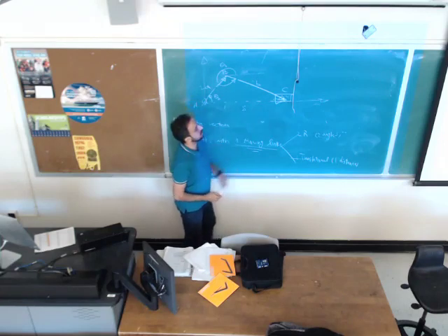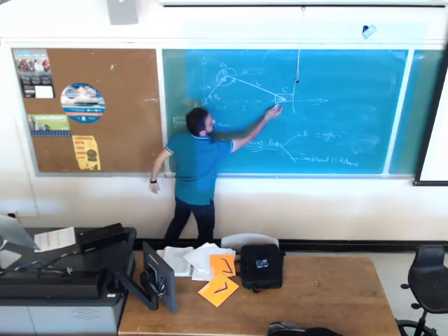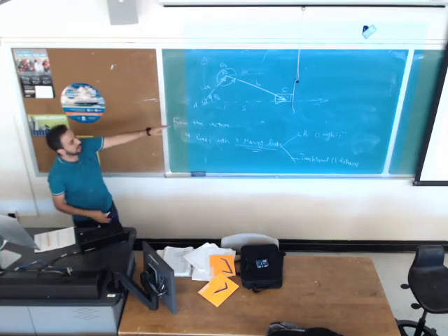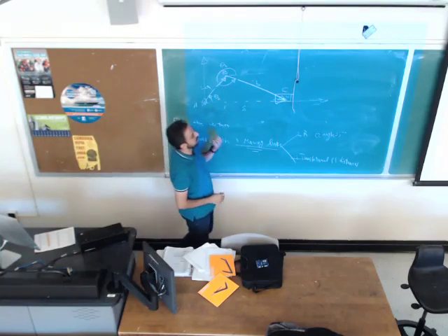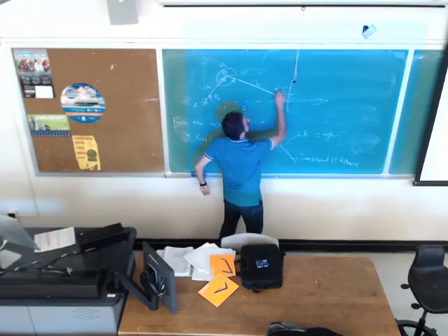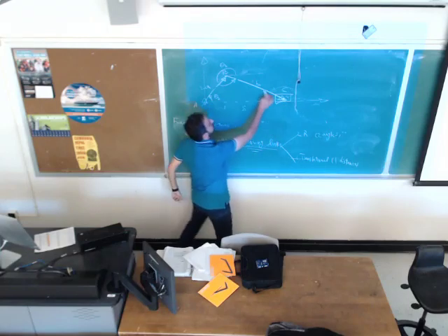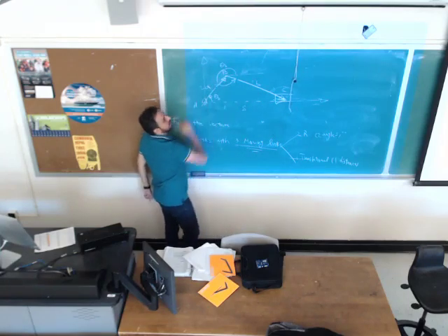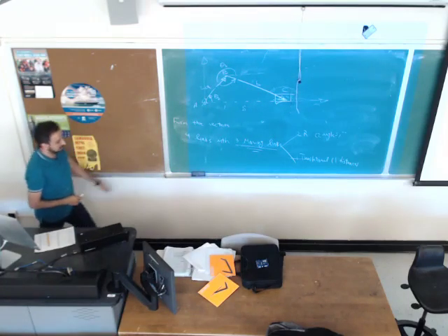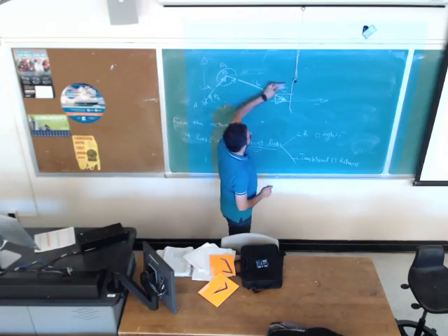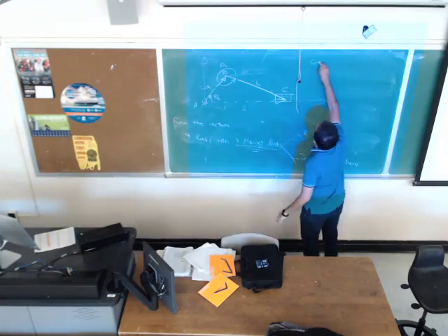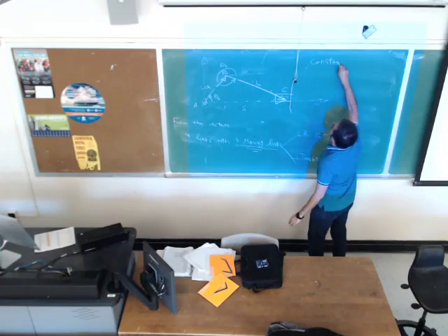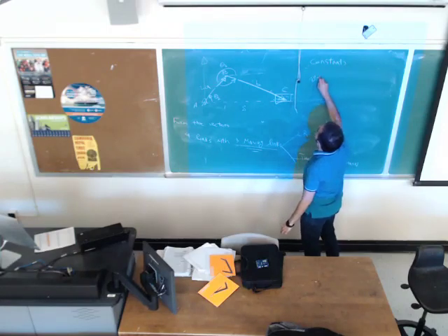Link 4 is a slider, so the distance would be the variable, which is S. We don't have any more angles in this problem. Don't count this angle, it is for the link which I already have over there. Then write these constants and variables.